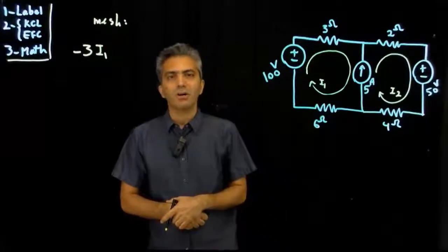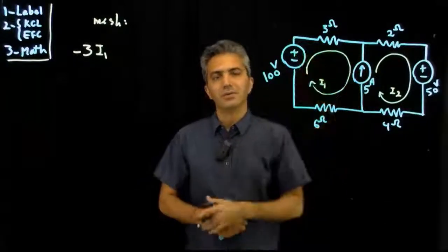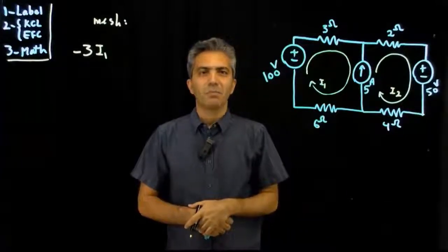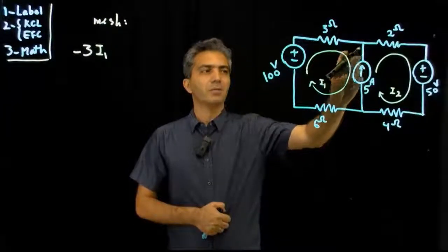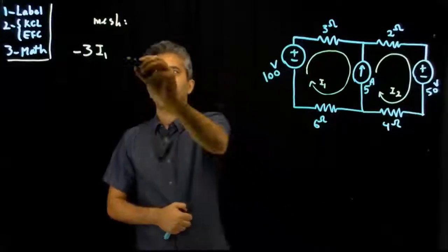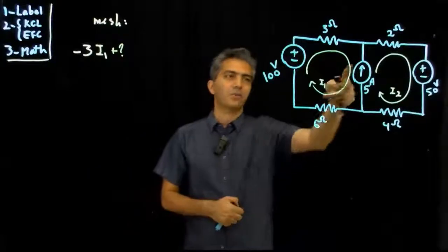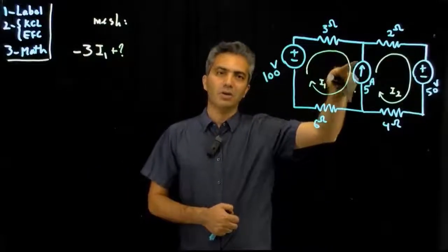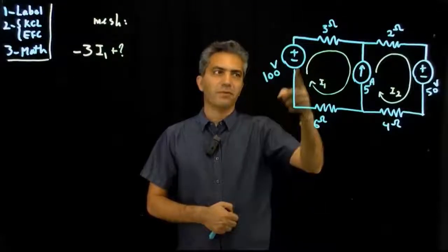But as you recall, for a current source, the current that is passing through the source is known, but there is no equation that describes the voltage across the current source, and therefore I'm stuck right here. Like, I don't know what comes next. I either have to identify a new unknown and move on, or I have to find a workaround.